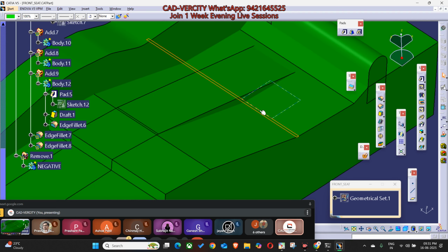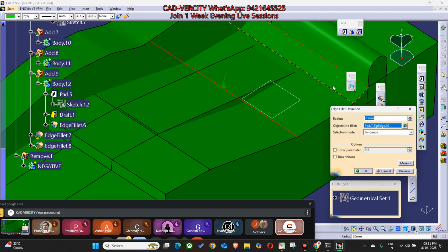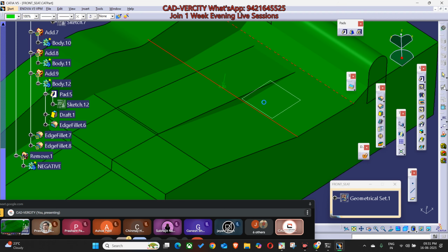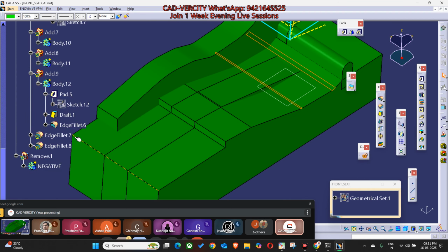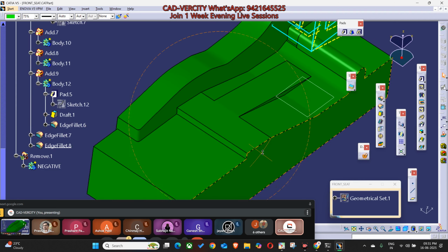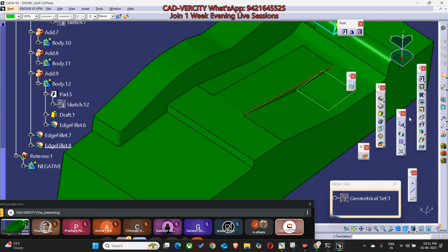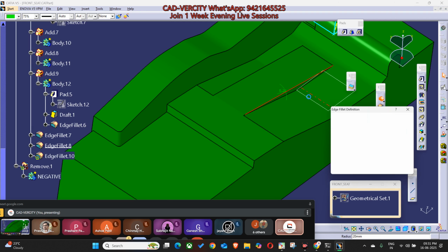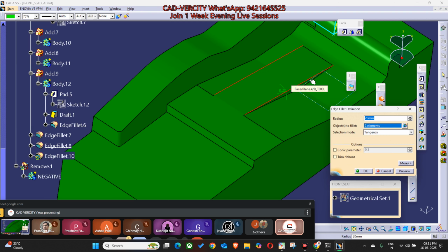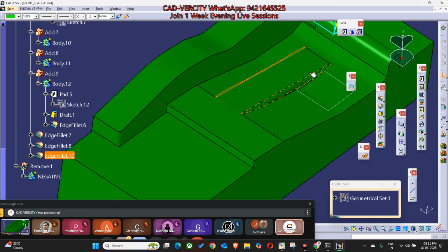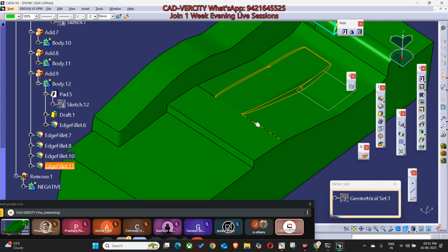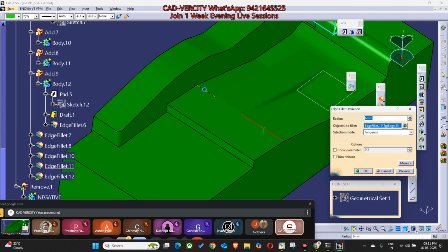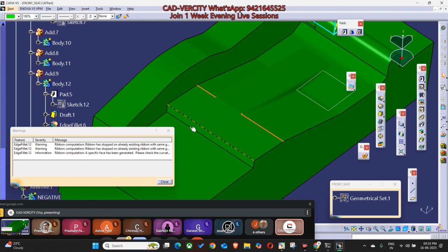Again, same. Double click on this one. Add this in the same fillet. Okay, done. Define, update. This is a fillet. I can apply fillet on this one. Let's say 6 mm. Done. Again, apply fillet over here 6 mm. Enter. On this edge 6, 6.